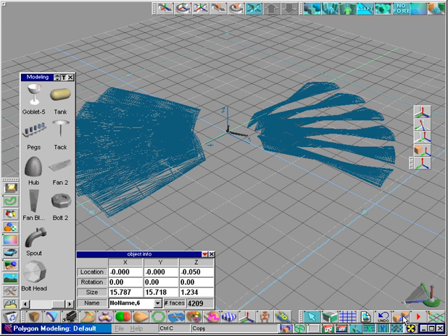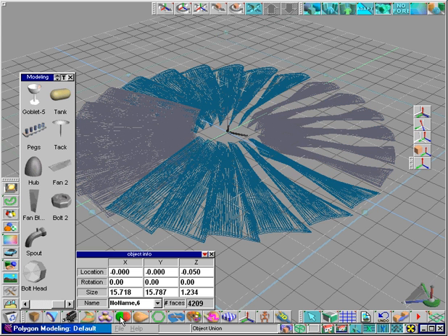Copy the assembly one more time and with the axis active, rotate it in Z -90. Hide the axis and normalize the rotation. The geometry will rotate +90 in Z. Boolean the 2 sets together. We now have a completed fan blade assembly.